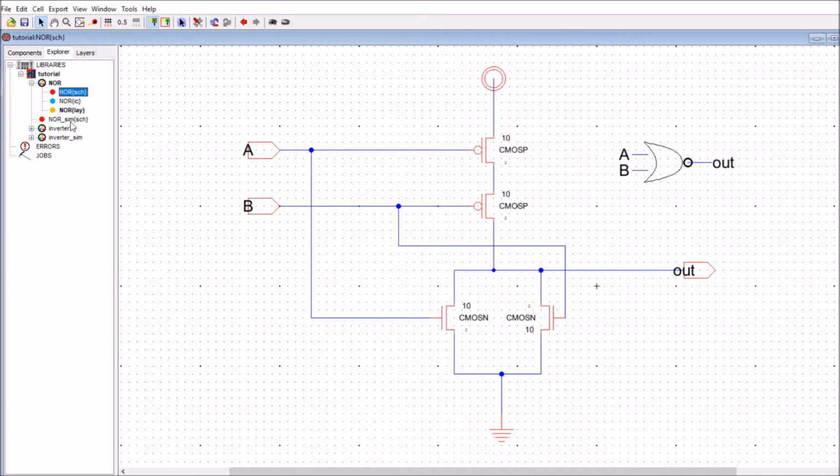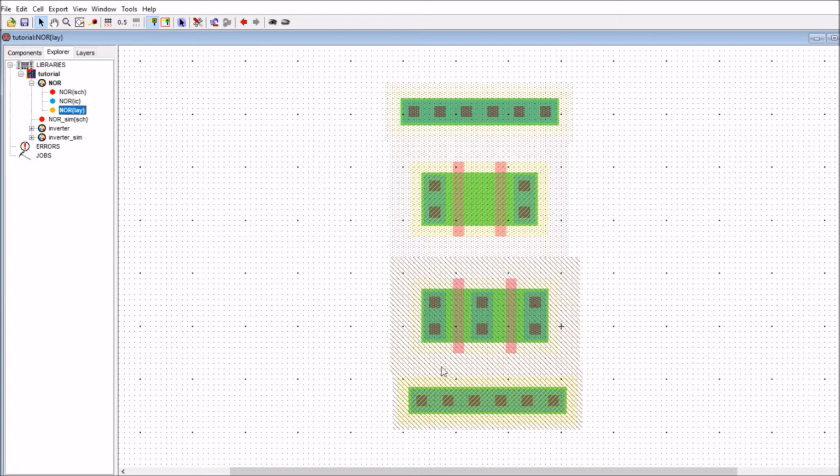So we head into the layout, then both of these are going to go to ground. So left click, right click, left click, right click. So this is our ground. And in this instance, one of these is going to go up to VDD. So this one here, going to VDD. So we can think about this one here as being our A input, and this one here is going to give us our B input.